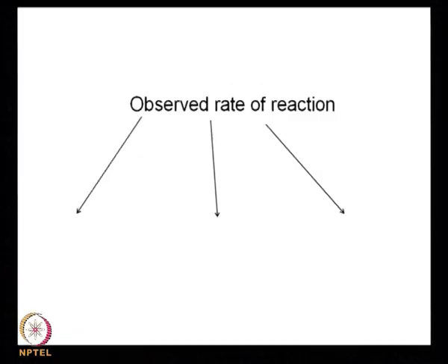Now, mass transfer limited regime is a regime in which mass transfer is the slowest step, and intermediate is where reaction and mass transfer are equal in terms of their speed. So, in the intermediate regime, how do we quantify these? So, these are the three regimes that I discussed: reaction limited, intermediate, and diffusion limited.